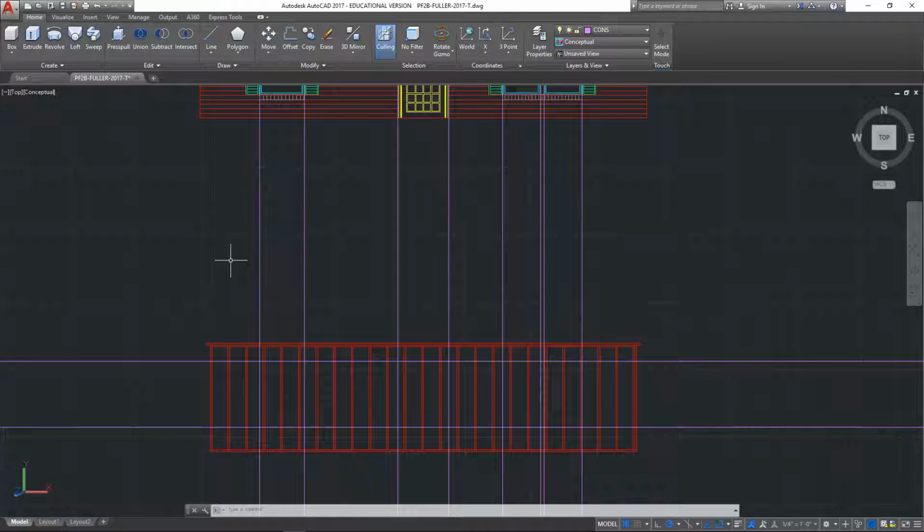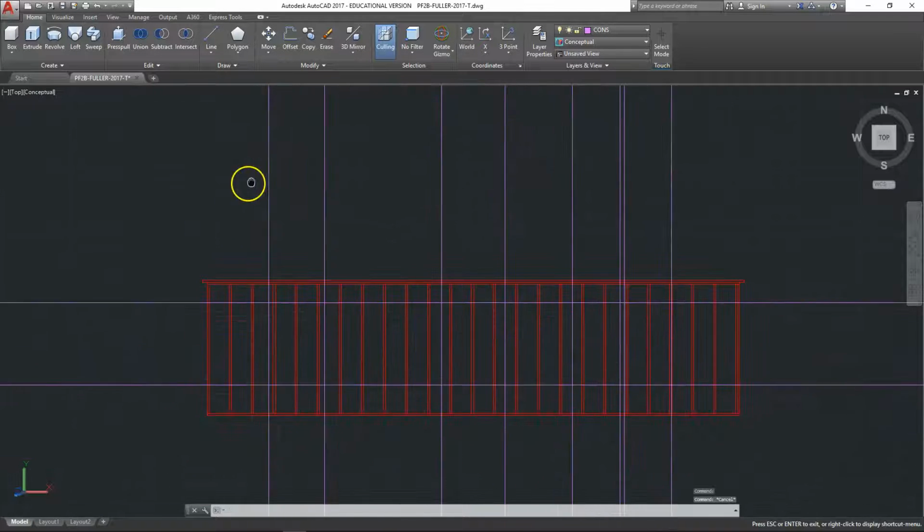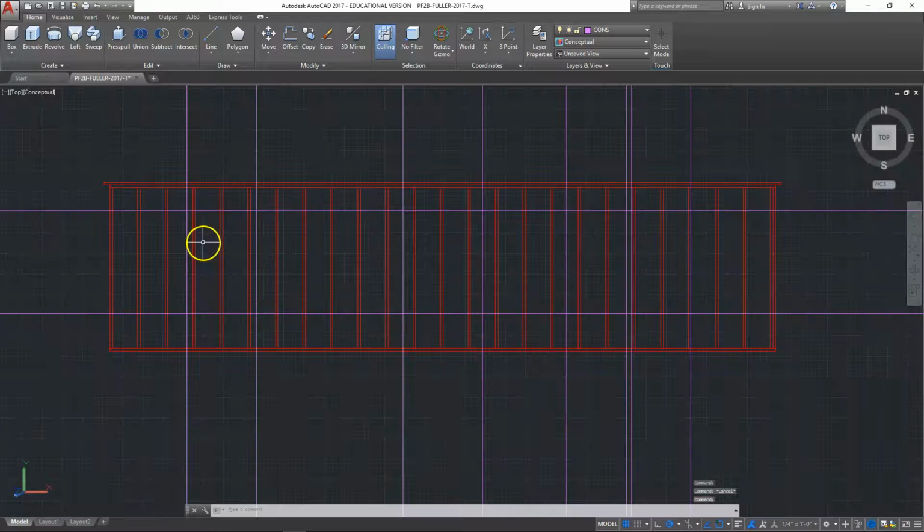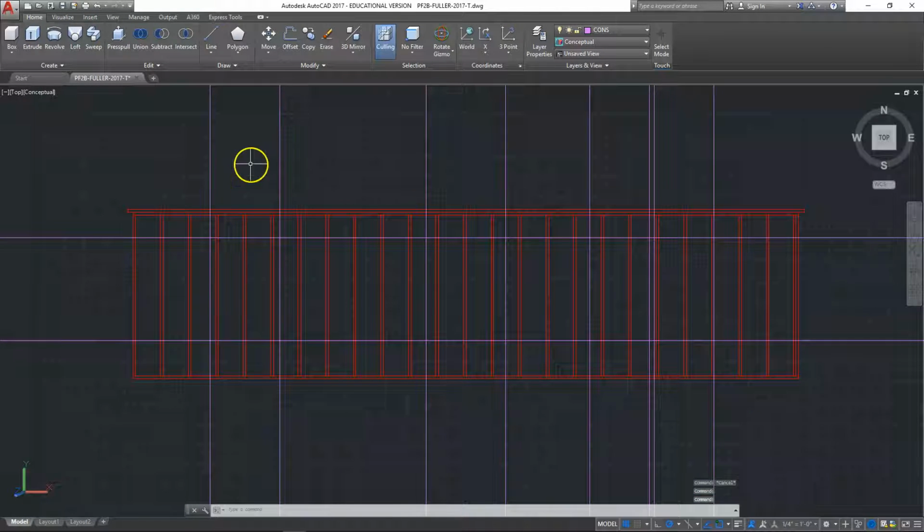To sum this up, I'm actually going to start the front wall 9 3/8 inches inset from each end. That comes from adding the 5 7/8 inches thickness of material outside of the framing core and an additional 3.5 inches to account for the width of the wall frame coming into the front wall. This will all make more sense later.